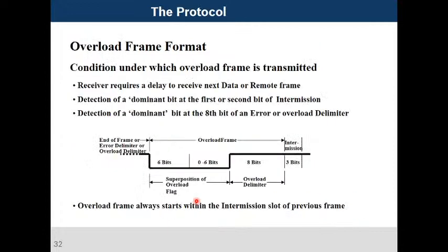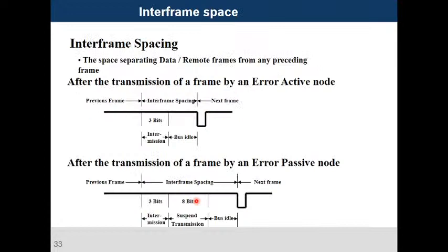Okay, the overload frame. If you have loaded one frame already and you try to load the same frame again, then a collision will happen. That will be detected on the CAN frame and reported to the microcontroller. The microcontroller will react based on that, and you should take that into your design as well. The interframe space, already I have mentioned, a 3-bit interframe space is required.